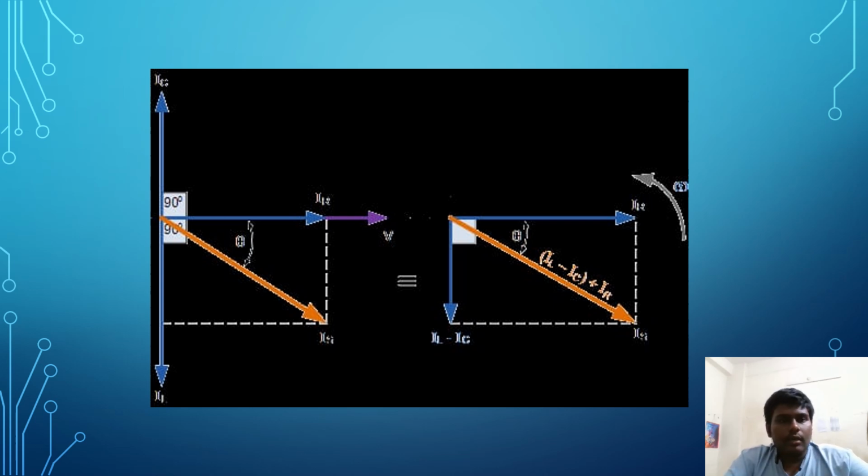And when we get to the phasor diagram, it is clearly seen that the current passing through the resistance is in phase with the voltage that we connected in parallel to both the resistance and inductor, and we can clearly see that the current present in the inductor is lagging behind the voltage we connected across this resistance and inductor.